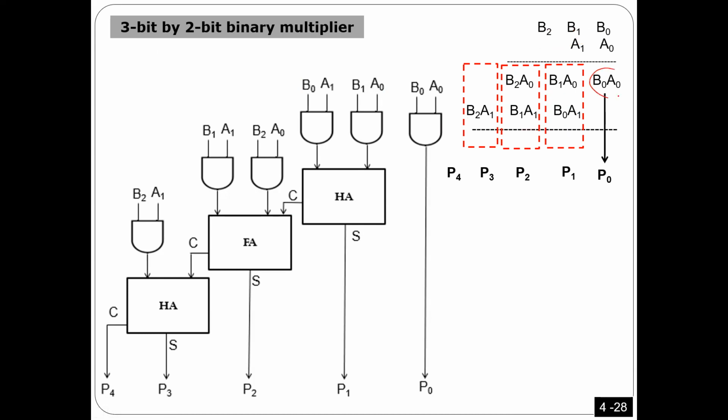And then once you have this, all of these operations can be calculated using AND, okay? Once you get this one, this will be the first output, and that's exactly what I did here. I got the first output. To calculate these ones, I need to add. I calculate these 2 values, and then add them together using a half adder. So that's what I did. I have a half adder here, and then I got B1. Okay, let's look at the next one.